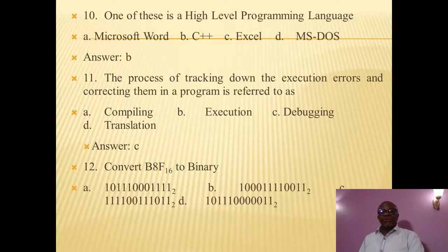If, on the other hand, you want to convert binary equivalent to base 16, it's as easy as ABC, whereby you just put the binary number and group it starting from the least significant figure, 4 bits by 4 bits. So if you get the first 4 bits, you'll find its equivalent in base 16. The second 4 bits, its equivalent in base 16. The third 4 bits, its equivalent in base 16. So it gives you what you want as easy as that.